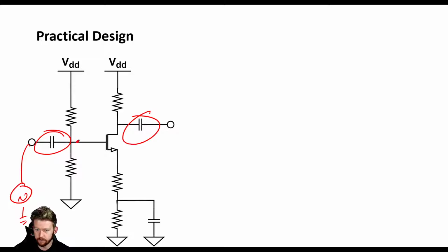And what these capacitors do is that they block DC. So this DC level isn't going to be able to make it through, but at AC, which if this is high enough, like maybe 10 kilohertz, it's going to be able to pass directly through this capacitor. So our AC signal is going to make it directly to our gate, which is important. And kind of the same thing on the output. Remember, we have a DC level of 6 volts here, and we may not want that passed through to our load. So this will block it and make it to where our load only gets the AC level. So throwing these capacitors in here, again, 10 microfarads is a good value, is going to help isolate those DC signals.